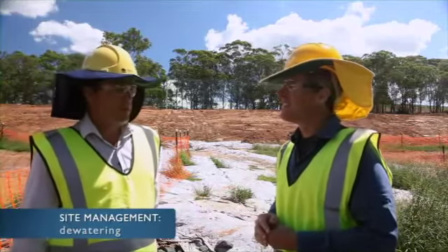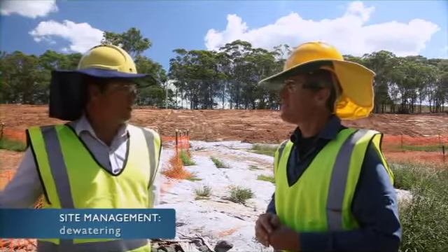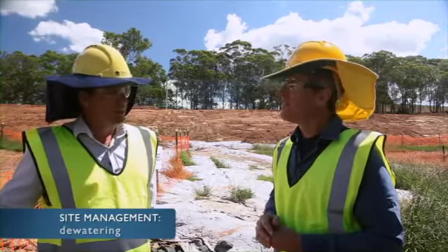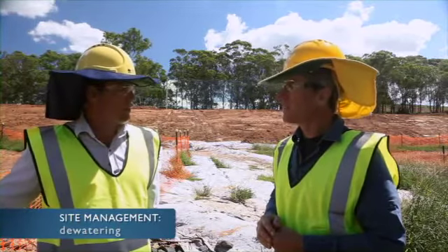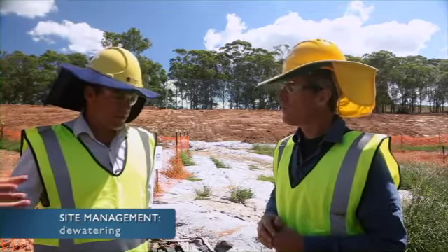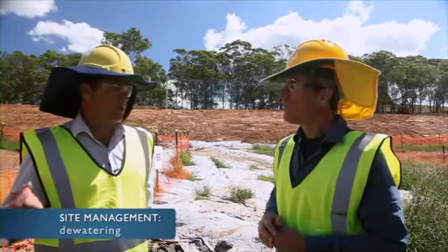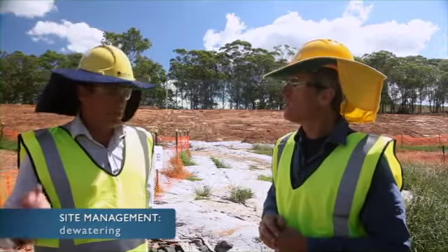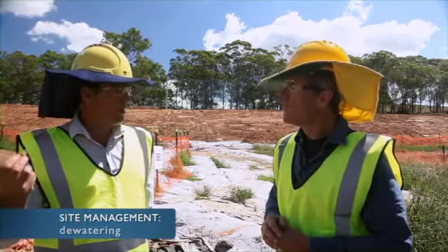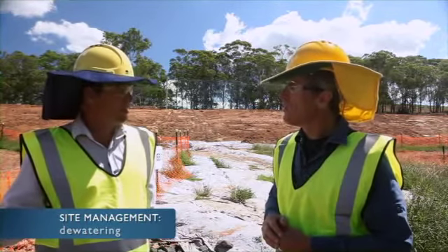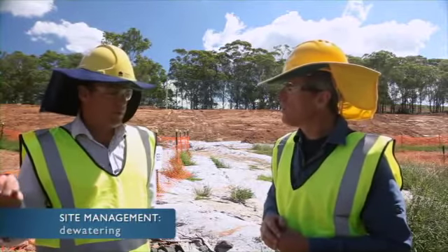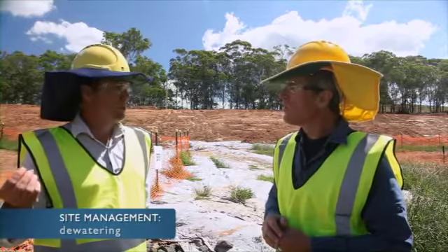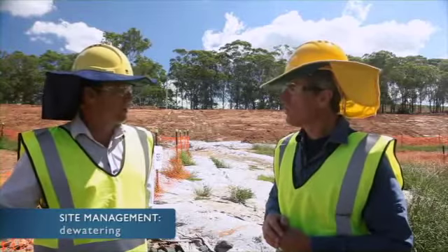No, Pete. It's our expectation that all dewatering activities on our construction sites will be done in accordance with a site-specific work method statement. And that work method statement should detail several key things. Firstly, that there's training of staff that are going to undertake the activity, that the information on that training or the key elements of that is included in inductions onto the site. The work method statement should also have an approval process to commence each of those dewatering activities on the site.